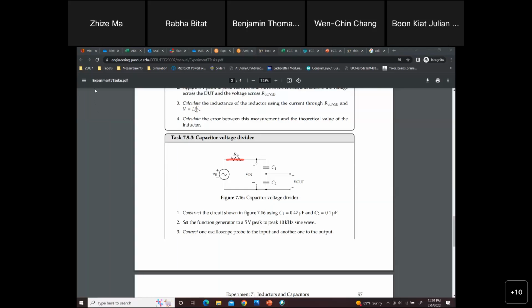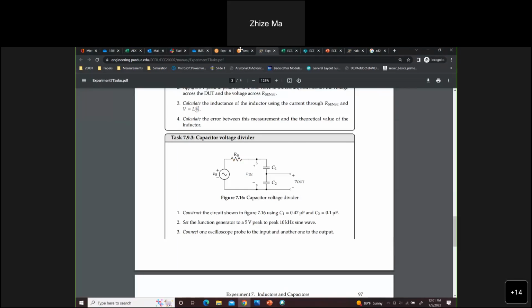And I saw there is another question, for the capacitor. There's a code 2A103G. What you need is 103. That's the 3-digit number you will need to use.